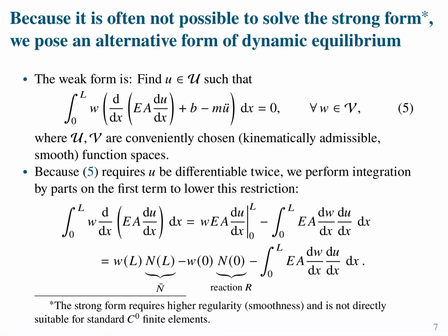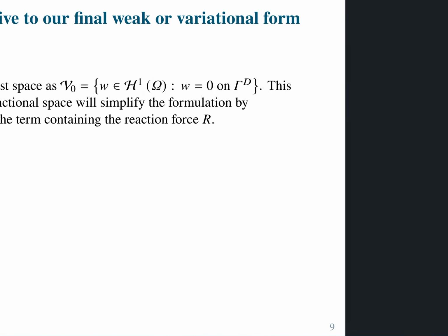We don't know. We can control the error. We refine. Does it improve? Yeah, more or less. So we refine again. We have criteria to do convergence, right? We can have these a posteriori error estimates in our finite element mesh and then say, well, maybe if I refine on this area, it's going to improve. Yes, it does. So we can control the error. All right? Okay.